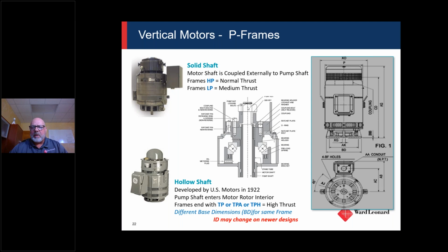And then there are a couple of things you have to do if you're familiar with how to apply these. You will set the thrust on it. As the motor turns on, it's going to have some lift to it as the pump is doing its stuff, so we can factor that in to how you apply the motor. Solid shaft is kind of the same, just a different method.